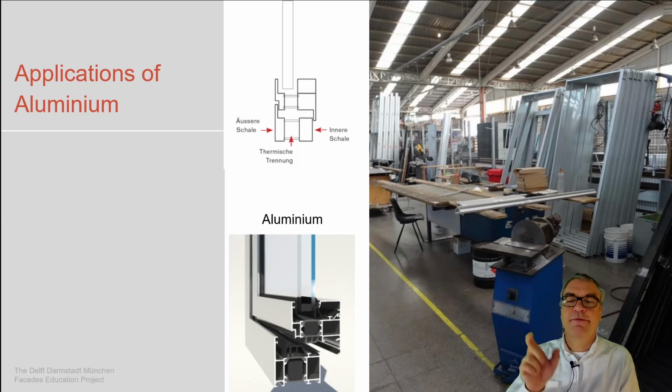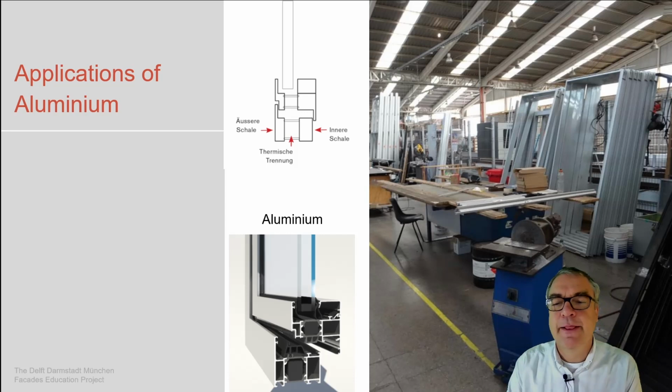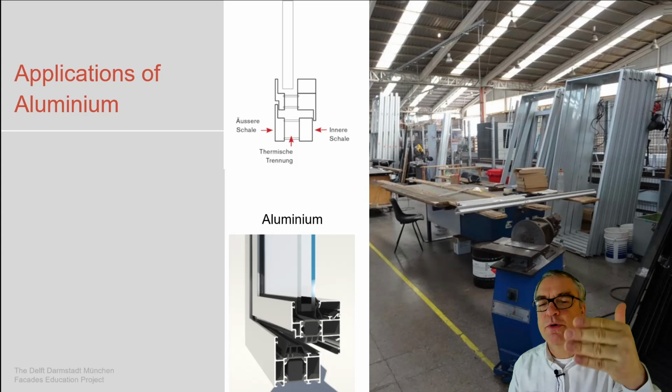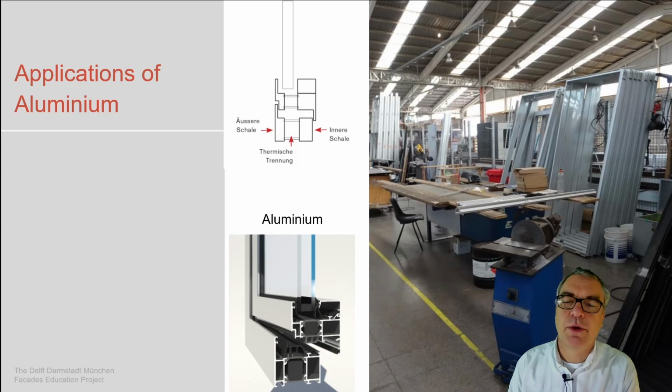If you want to continue with the manufacturing, this is an aluminium profile of a window system. Allow me to stay here for a minute. As I said, thermal conductivity is quite good for aluminium, so the energy transport works well. So we need to have a thermal break from the outer surface to the inner surface to reduce this thermal conductivity, reduce the energy transport.